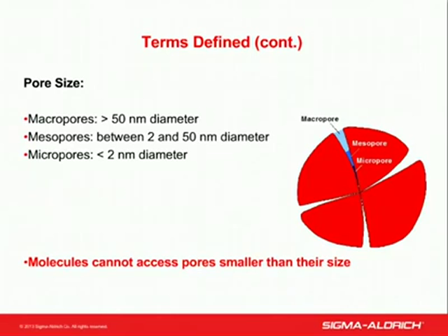Pore size. Pores are classified according to three main groups depending on their size. As a general rule, an adsorbent containing larger macropores is used for large semi-volatiles, and those with mesopores are used for volatiles that are liquid at room temperature, and the smallest pores, the micropores, are used for very volatile organics and inorganic molecules that are a gas at room temperature.